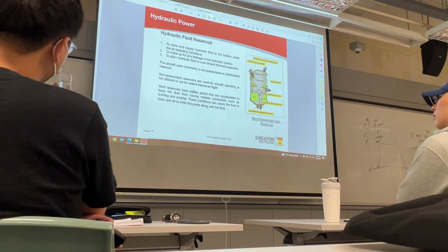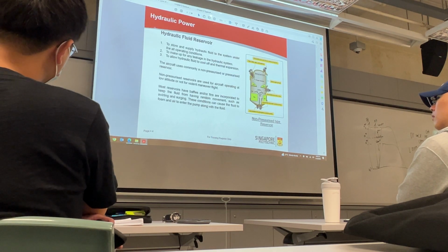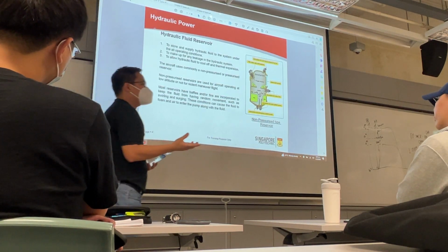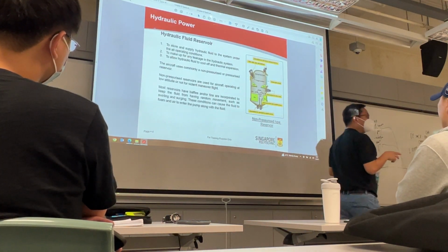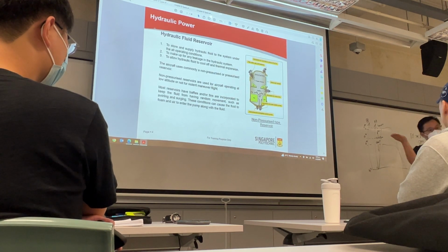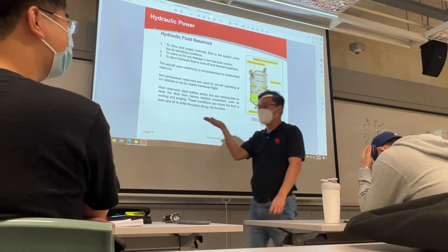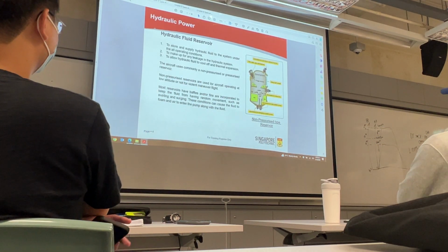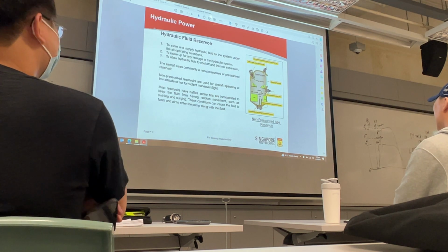For the pressurized one, they will pressurize it. What happens? When you pressurize this area and the fighters do inverted flight, the fluid must still be pushed up and supplied to the pump. Then you won't have any cavitation or sudden failure of the actuator to push. Imagine you turn left, then you turn left inverted, and that's the last position. Then you say, never mind, landing gear now. How to lower landing gear now? I don't know, I never tried before. I think cannot. Don't ask me whether possible or not.